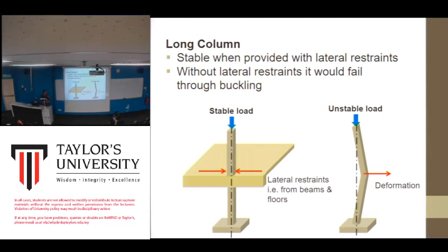That is considered a single column. Similarly in your assignment, from the ground to the roof, if possible, all the columns should be at the same position, except for certain areas. For example, above the ground floor, you might have a balcony.